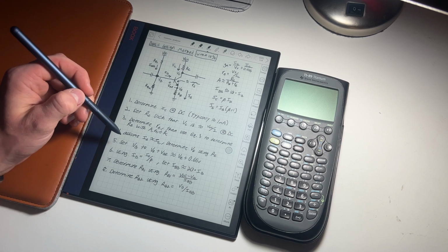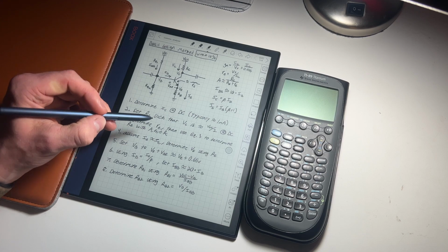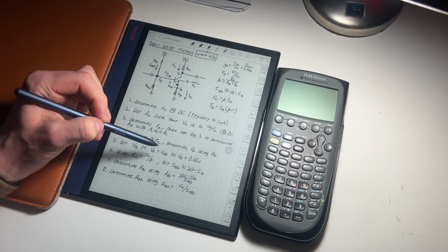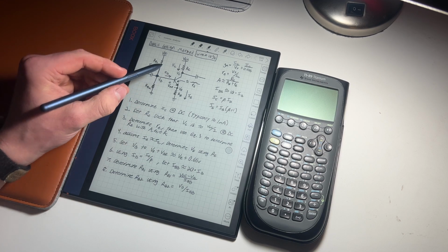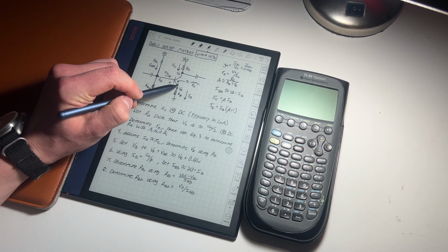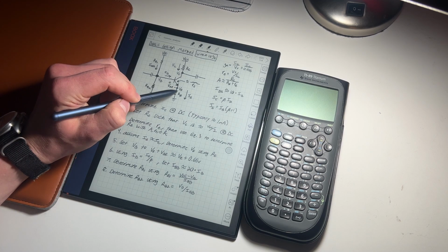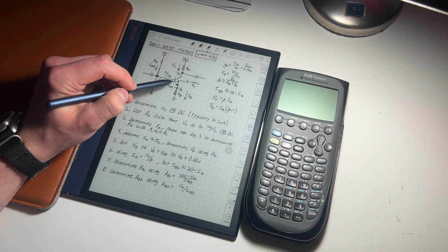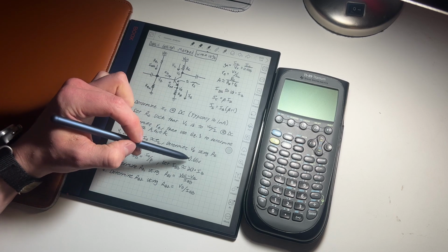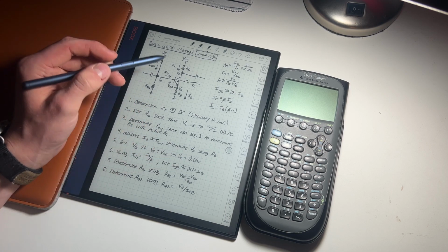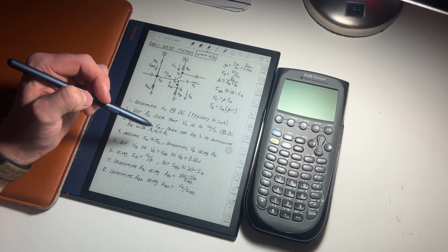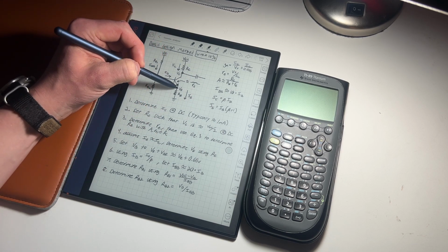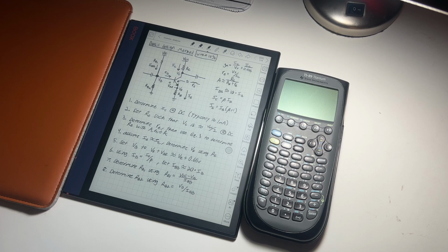From there, you set VB to VE, your emitter voltage, plus VBE. Now, like I said earlier, there's a diode junction here. And a typical silicon diode, which a lot of transistors are made of today, has a 0.65 volt drop across it. So all you have to do to find the voltage at the base is add 0.65 to the emitter voltage here.